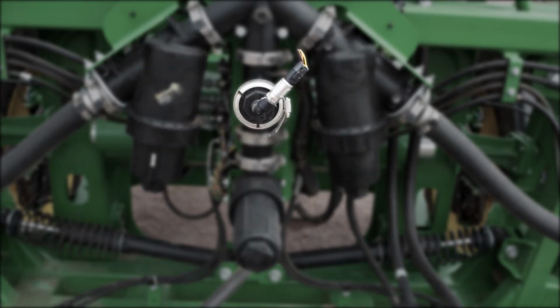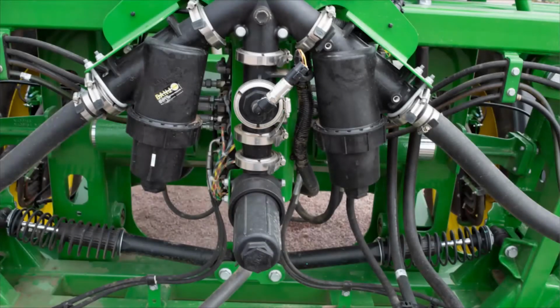This is where our boom pressure sensor is located. Whether you're operating ExactApply or not, the boom pressure sensor is located here. When you're cleaning out the sprayer, as you're doing flushes, if you don't regularly do a clean water flush, this is a good place to look because there are just a couple real small dead spots in here. Or if you're seeing pressure not get to where you think it should be, it's a quick and easily accessible place to clean up any additional residue.